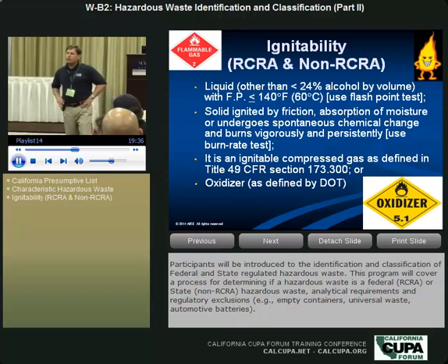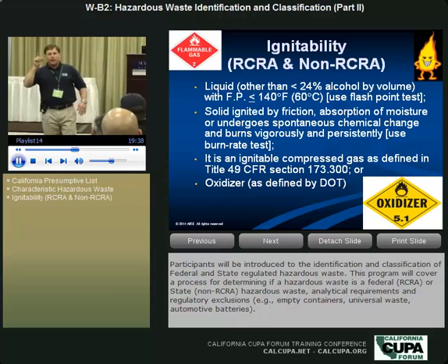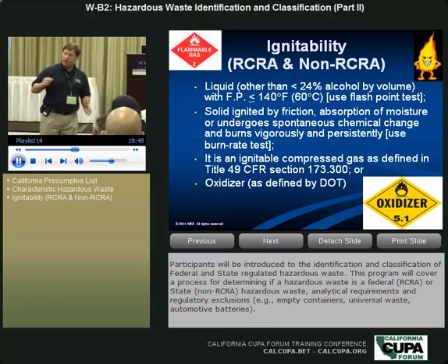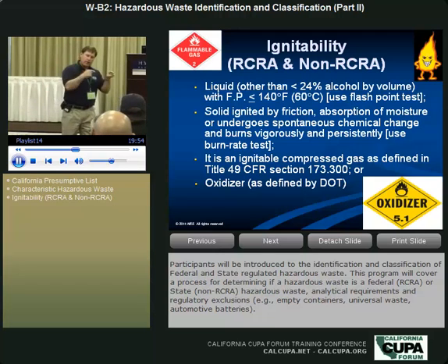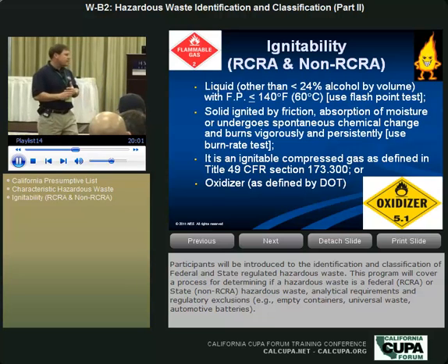And it turns out that for an ignitable waste that exhibits an ignitable characteristic, the definition is the same. There is no difference. So if it's captured by RCRA, we capture it in the state. And it's a RCRA hazardous waste. It's both. We manage it as a RCRA hazardous waste. We can assign a state waste code and a federal waste code to that waste stream. And if it's used in a closed-cup Pensky-Martens test methodology where the flash point is at or below 140 degrees Fahrenheit, 60 degrees Celsius, hazardous waste.